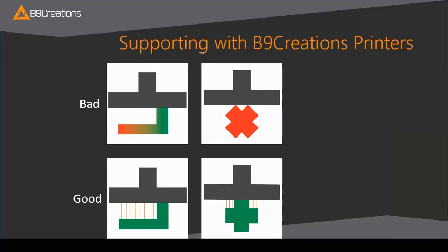The first graphic on this slide shows a model that starts off printable, but the next layer has a large overhang. As denoted by the transition in color, the green sections will print fine, while the yellow may hold on to the model beside it, but as you get further away, such as in the red areas here, the higher the chance the model will fail. The second graphic shows that if supports are added in the discolored areas, the model will print without any issues.